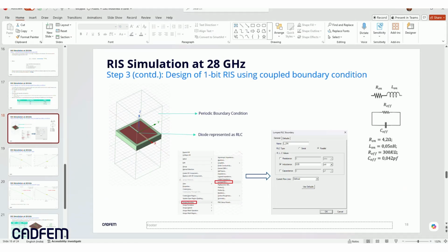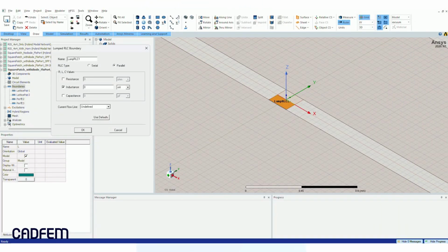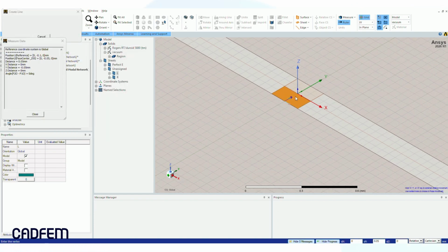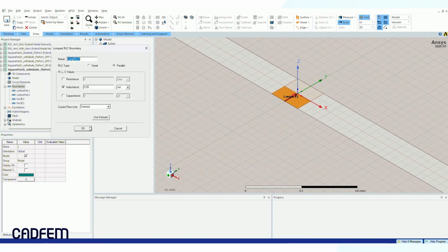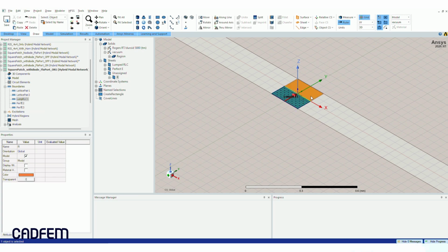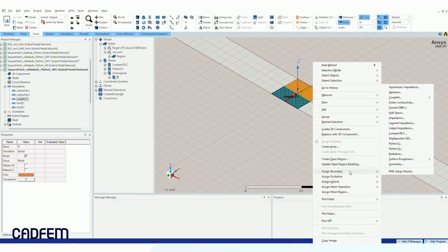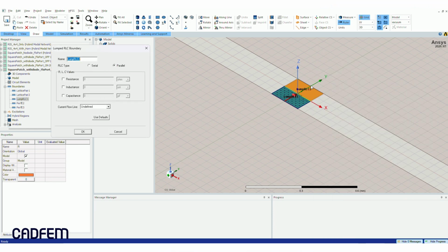This pre-simulation verification helps identify potential setup inconsistencies before computational resources are committed to the solve process. Once the analysis begins, HFSS calculates the electromagnetic response of the array's unit cell and generates the data required for subsequent performance evaluation.